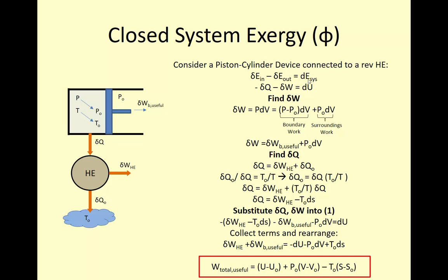It's a quantity that can be fully differentiated. Okay, so we can rewrite this E in and E out in terms of Q and W. So we say this del Q minus del W is equal to dU of the system. So it's a Q out and a work out. That gives us negative terms. So the in goes away. We're just looking at the outputs at this point.